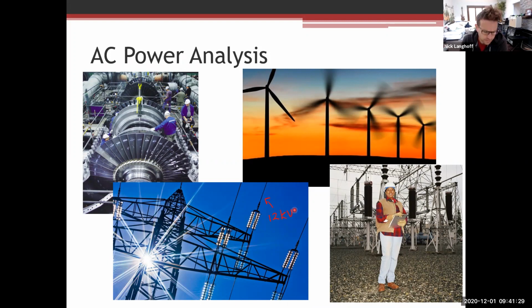Is that nearby? The power lines outside of your house or on the street, are those the 12 kV lines? I forget. They go higher than 12 kV for sure. But anyways, the voltages are way high and the currents are really low. So you minimize power loss.